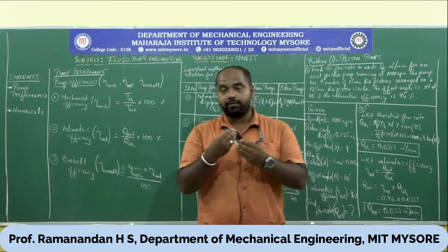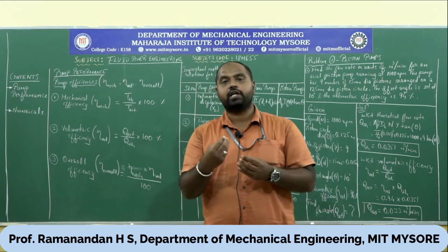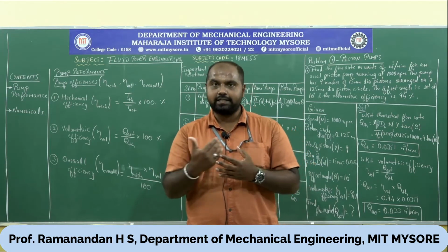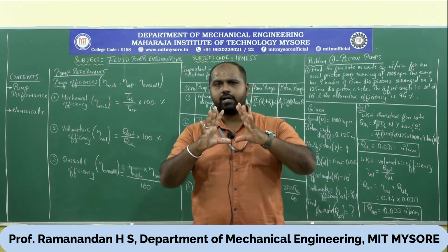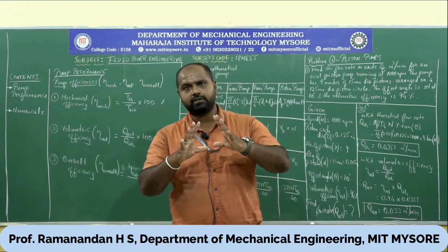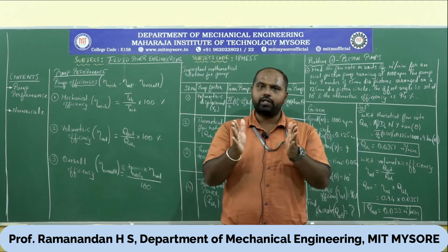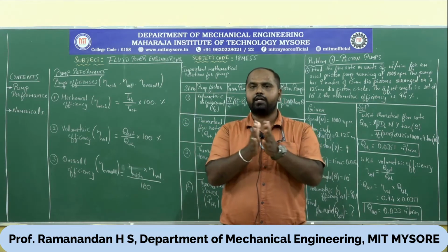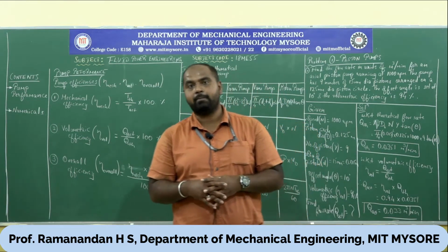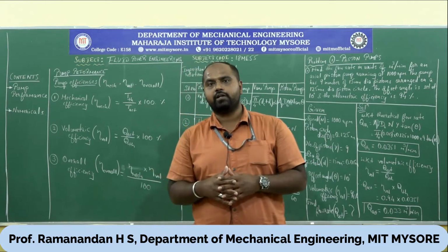What is the tolerance or clearance between the elements? What is the eccentricity? What is the width or the diameter of the gear or vanes? And what is the eccentricity between the vane rotor and the cam ring, if it is a vane pump? All those things play a vital role.